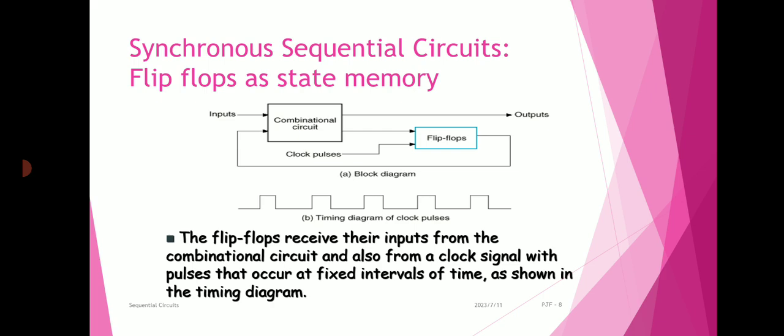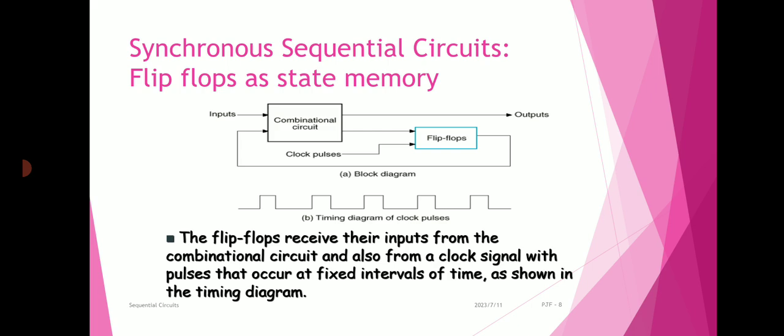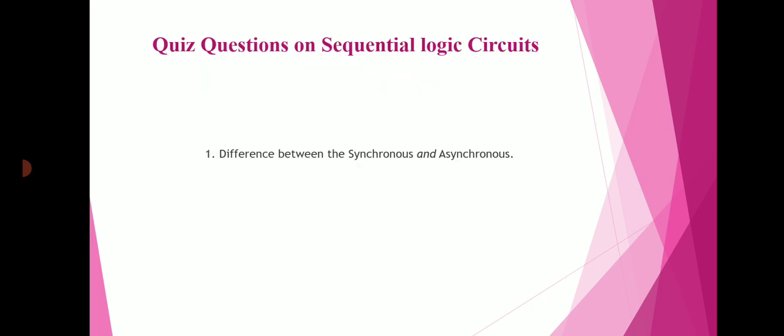The major disadvantage is complexity. We say complexity because these circuits contain more components to implement, and there are time constraints. When designing a sequential circuit, it can be challenging to ensure that the timing of the inputs and outputs is correct. Then only can we transmit the information or the pulses. Testing and debugging are also more difficult compared with a combinational circuit because of its complex structure and state dependent outputs. So the major disadvantages are complexity, timing constraints, and testing and debugging.